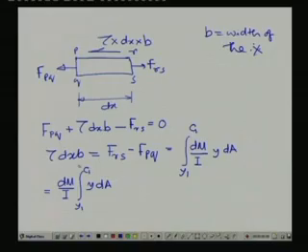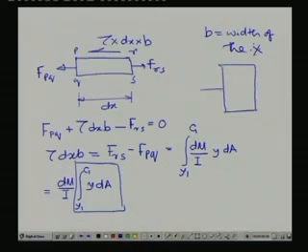So, what is this particular term, y dA integral y1 to c1? If we look into the cross section, this was the area where we have found the force. This was y1, this was c1. If we consider somewhere a centroid, then this is the distance from the neutral axis of the beam section.